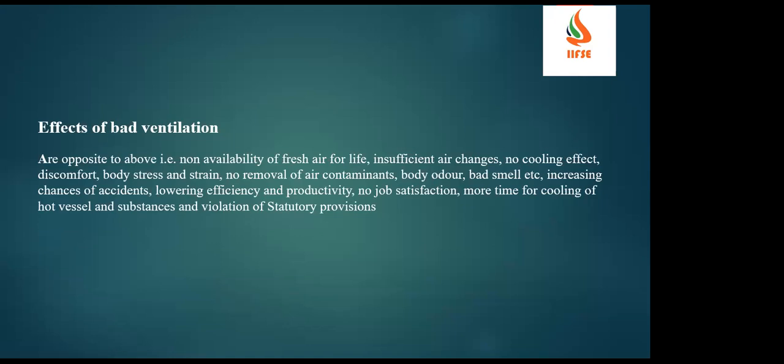Now we'll see the effects of bad ventilation. It is completely the opposite of what we have seen before. A non-availability of fresh air for life and also insufficient air changes, no cooling effect, discomfort, body stress and strain, no removal of air contaminants, body odor, bad smell, etc., and increasing chances of accidents, lowering efficiency and productivity, no job satisfaction, more time for cooling off hot vessels and substances, and also a violation of statutory provisions.